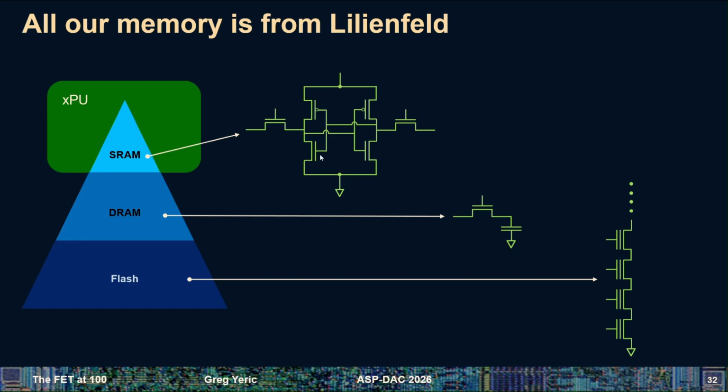That's an unstable circuit, so it's going to flip or flop between a 1 and a 0 state, a high and a low voltage, where the high voltage is the power supply coming in here. So it's going to flip one way or another and then stay there, and we can influence which way it flips with outside influence. That's this 6 transistor, 6T standard memory cell for a standard SRAM. And we're going to talk about that here in a second.